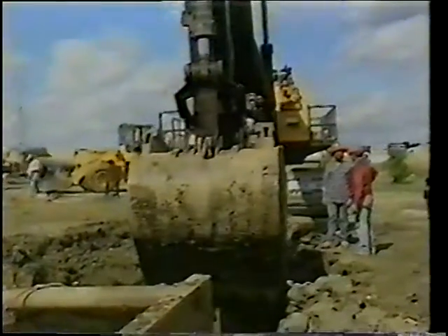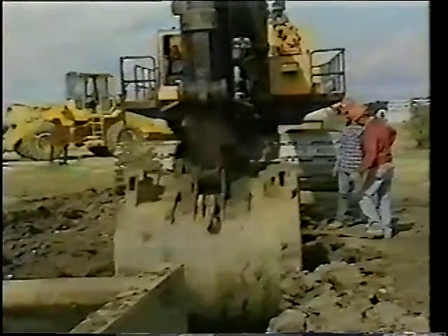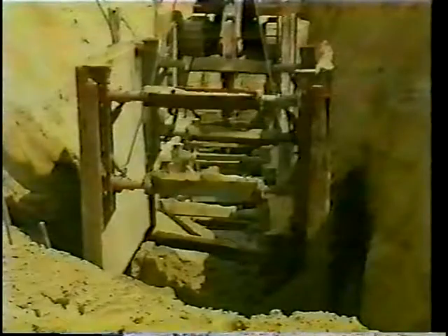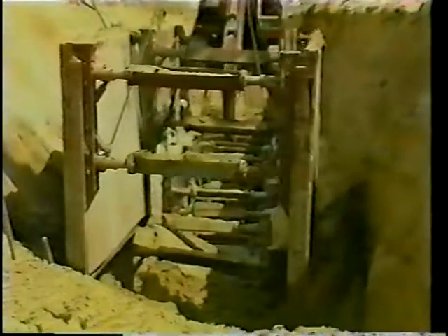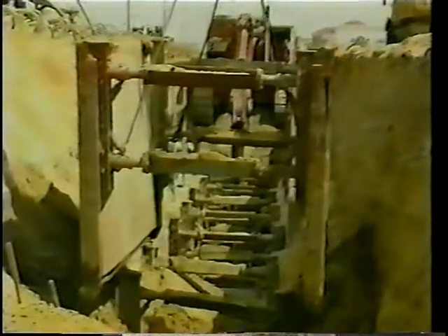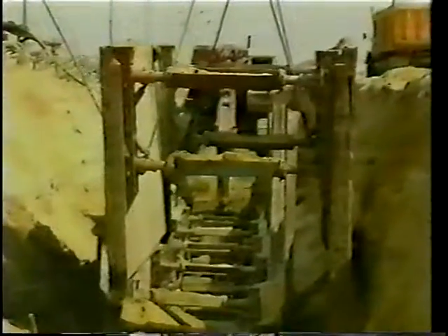First, trenches must be excavated so that the sidewalls remain stable throughout construction. A movable trench box may be needed to provide a safe working area by preventing the sidewalls from caving in. The box has to be moved with care to avoid damaging the pipe or disturbing the compacted soil. Trenches should be left open for the least possible time. Exposed trenches may destabilize, flood, freeze, or present a safety hazard. It is therefore good practice to excavate just ahead of installation.